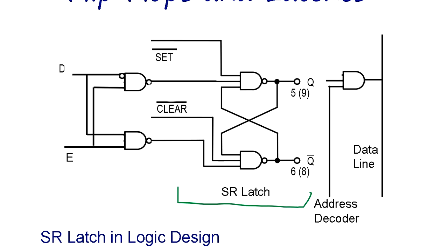Okay, and what happened is this is S and this is R input, and S and R normally high here, they never go low together. And if S, this is bar actually, S is high, this goes low, so same effect as set, and R goes low, it's an active low, so it's same effect as reset. So that's why set and reset latch.